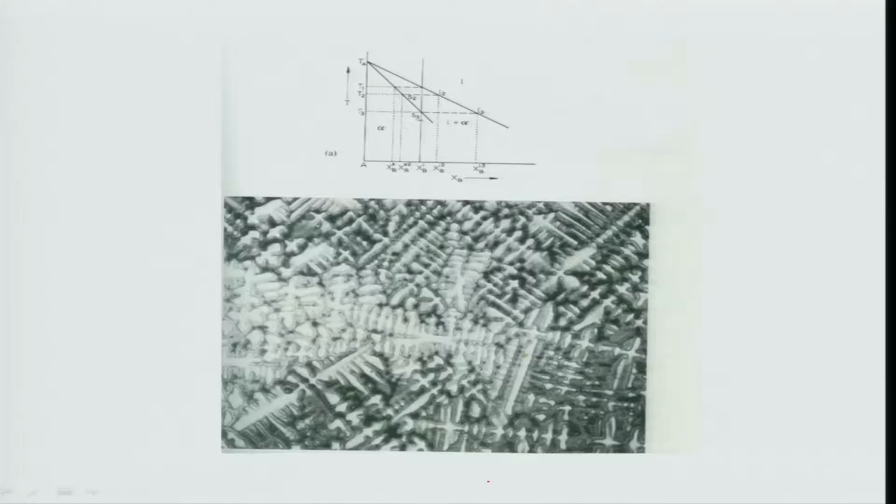Let me just show you a few pictures. Let us take this one. This is basically a picture taken in our laboratories and taken from the book of Professor S.P. Gupta, who himself has gathered it for a copper nickel alloy. As you can see here, this is a typical dendritic microstructure. We will discuss why dendrites form later. But if I clearly look at one dendrite, you can see the center is very light, but the peripheries are dark.